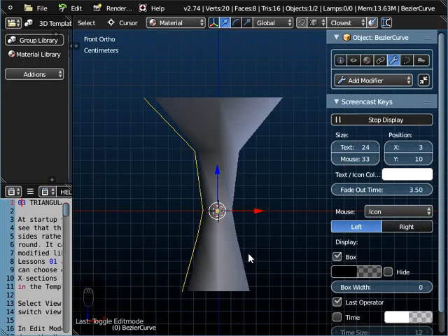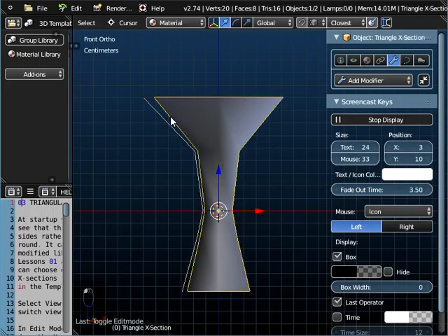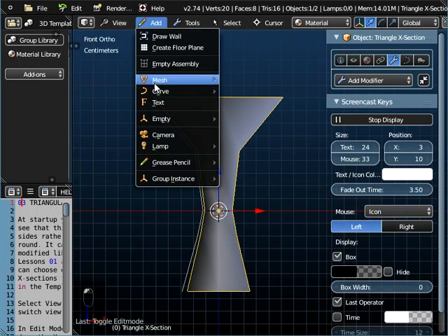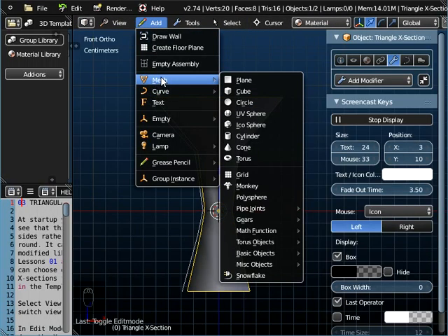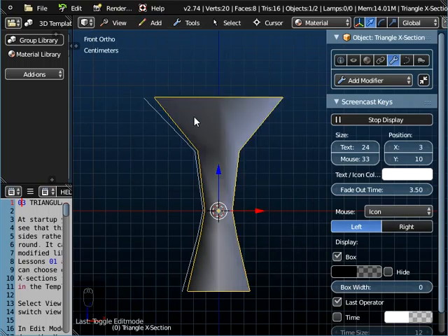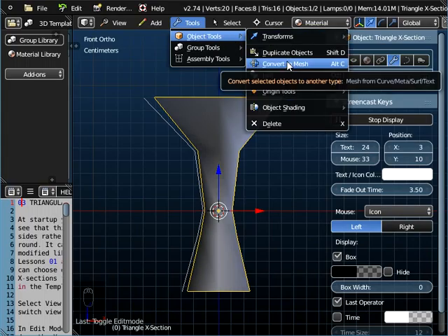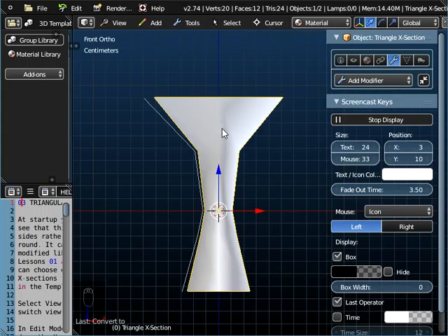So I'm going to stick with that shape at the moment, and I'm going to stick with that profile that I've got. Now, as I've said, this object here is actually a Bezier curve, and we can't print curves. We've always got to change curves to meshes. And we do that in FluidDesigner by highlighting the object itself and then going to Tools, Object Tools and Convert to a Mesh. And you'll see the colour change.